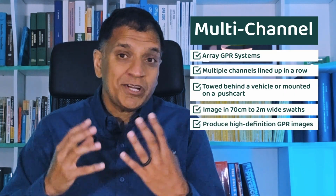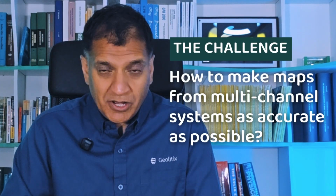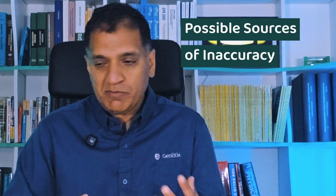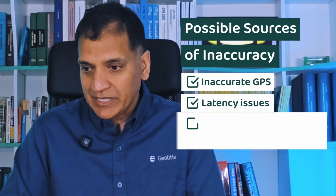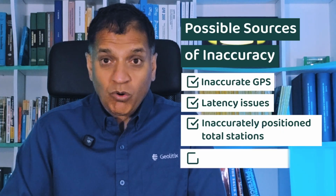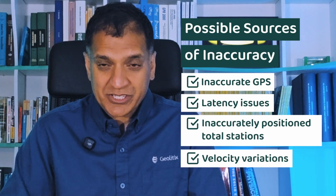Now, the challenge is, what do you do with those images? Of course, we can migrate the data and we see all our pipes or our archaeology very clearly, but we want to make the maps that we produce as accurate as possible. And we already know in GPR that there's so many sources of inaccuracy, be it GPSs that aren't exactly as accurate as possible, latency issues, inaccurately positioned total stations, or even not accounting for velocity variations. So there's lots of opportunities for inaccuracies in GPR. Let's not make mapping our pipes once we have the data into the software an additional source of inaccuracy.